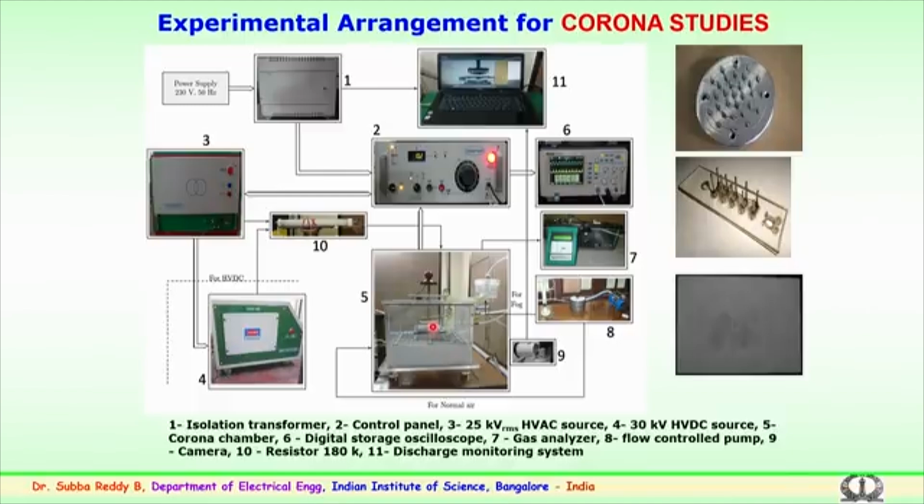The corona which is generated by AC or DC again consists of an electrode arrangement of this nature. You have simulation by using various needle structures of this type, where a uniform corona can be impinged on the test samples. For non-uniform corona, you use this type of needle arrangement. This impingement on the sample is continuously stressed over a planned period of time, with a planned cycle for moisture or fog, and the samples are evaluated. Samples can be 2 mm thick or 6 mm thick. These samples are evaluated after the experimentation. Surface morphological changes seen on the rubber samples are examined, and chemical analysis of the surface changes which have happened is carried out.